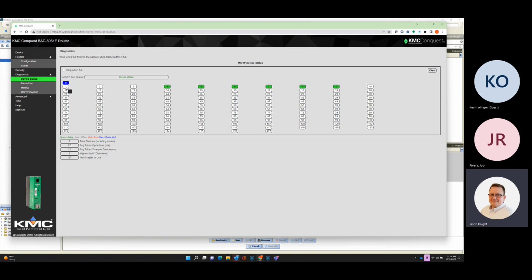Then you've got 2 devices as address 1. So what Distech recommends, and pretty much every controls manufacturer recommends, is that you start your network at 4 or higher. So you can see right here, oh, bus is unstable, analyzing. Something's not happy right now. What isn't happy? Go to the token usage, and you can see it pass the token.